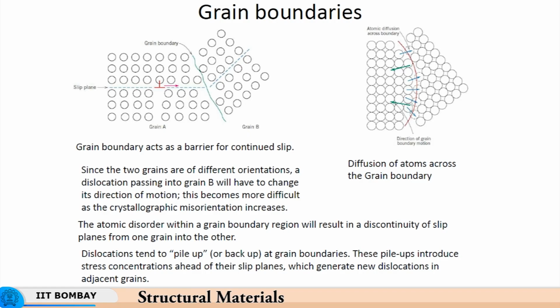So, below equicohesive temperature, the deformation happens purely because of dislocation movement, dislocations in the grain, and that deformation takes place because the grain is weaker, is more deformable. When I say weaker, it means more deformable than the grain boundary. So, grain boundary acts stronger, and therefore, it blocks the movement of the dislocations and results in work hardening. So, the grain boundary is not affected by stress at relatively lower temperatures below the equicohesive temperature.